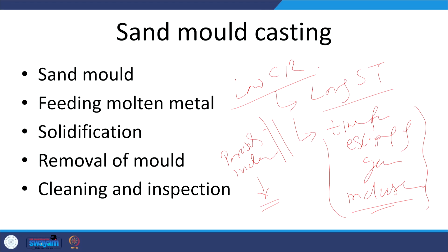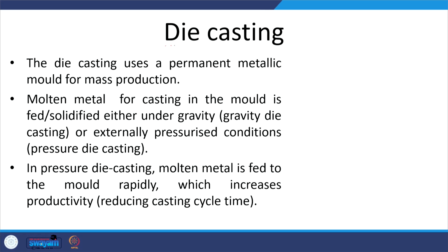But low cooling rate on the other hand will result in a coarse grain structure, and that in turn will lead to reduced mechanical properties. Okay. Now, we will be looking into die casting.